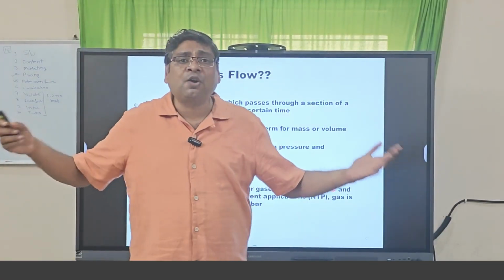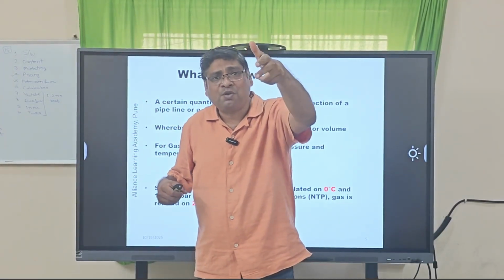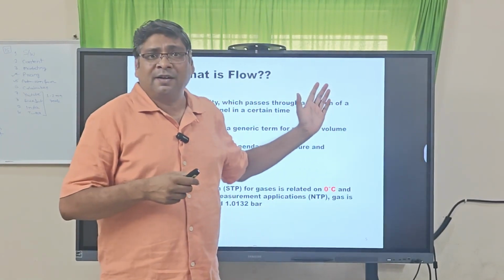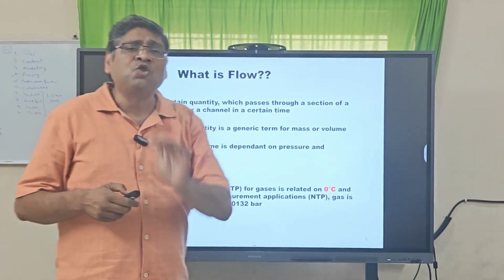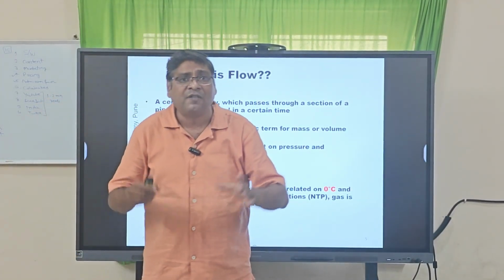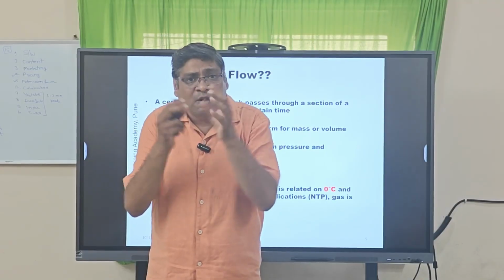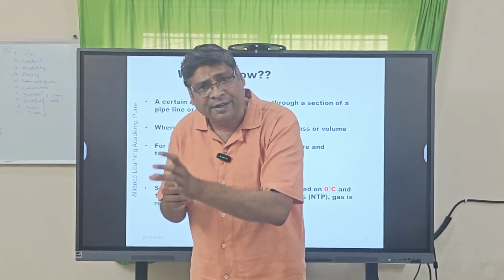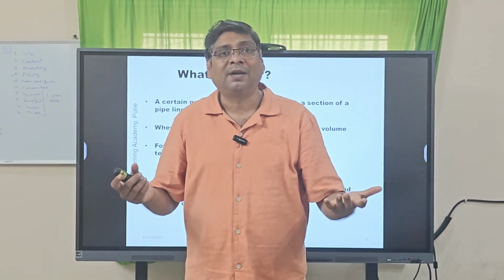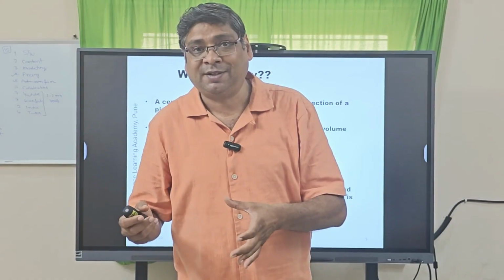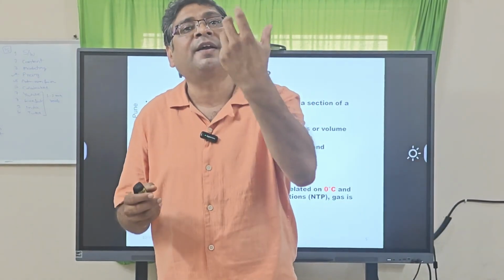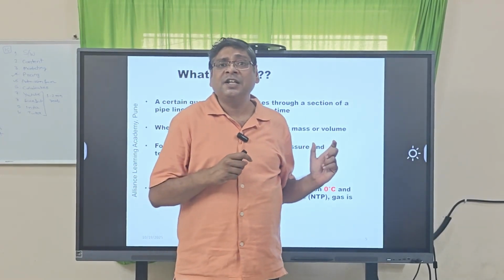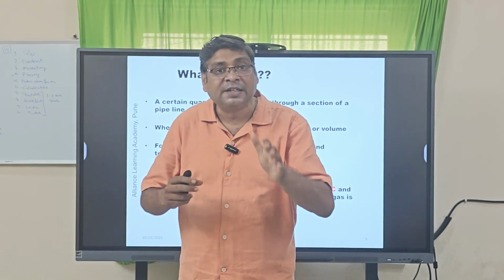Now, if I ask a question, what is flow? How many of you can give me the answer? Right? Now you can read it. In instrumentation, most of the time, you need not cram the definitions of these parameters. It is very simple. If you know its unit, like flow, m cubed per hour, or tons per hour, TPH, then with this unit you can give me the definition of flow, which you are not able to tell me right now. But after this session, you will always remember these definitions.